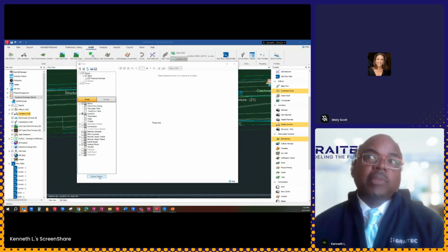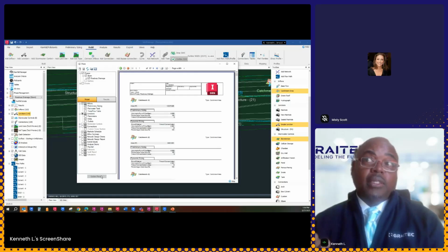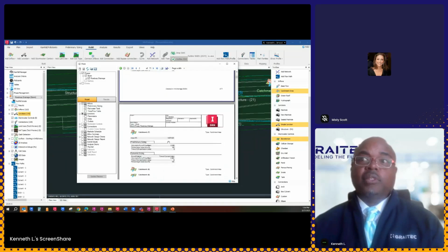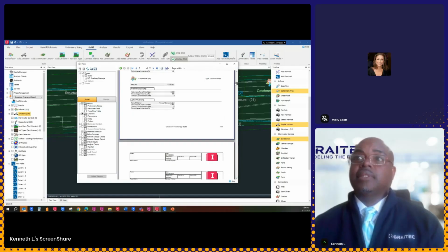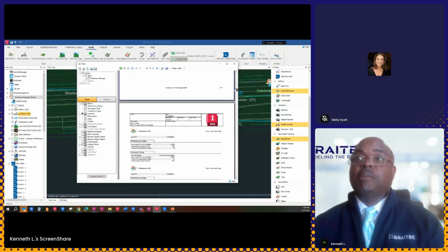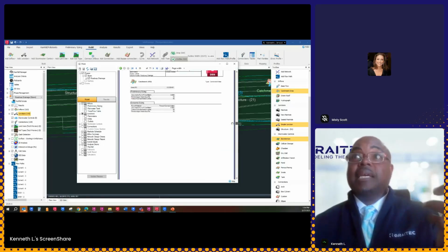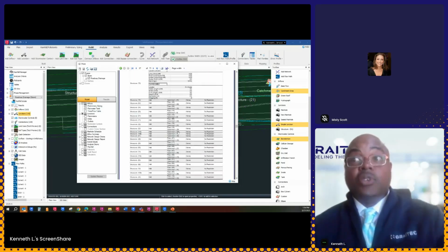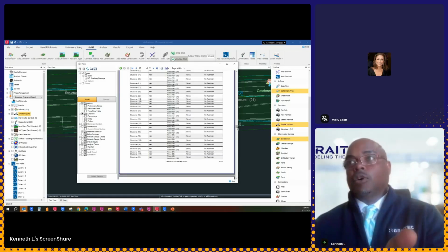So now if I come here and select update, it says, wait a minute, you've got a lot of stuff in this project that we need to get out into a report. And here it is. And it's just that straightforward. When you scroll all the way down, you've got inlets and preliminary sizing, things like that. And per inlet, it gives me my inlet type, my inflows, every piece of data, all my structures. Everything that I've denoted that I want to see over here is populated over here in my report.